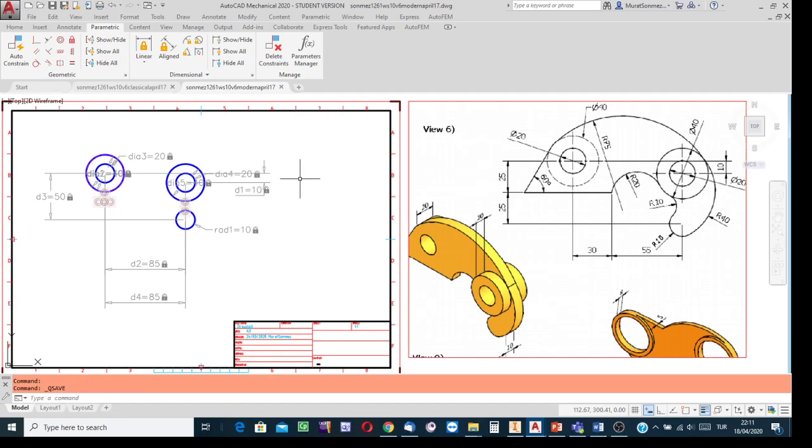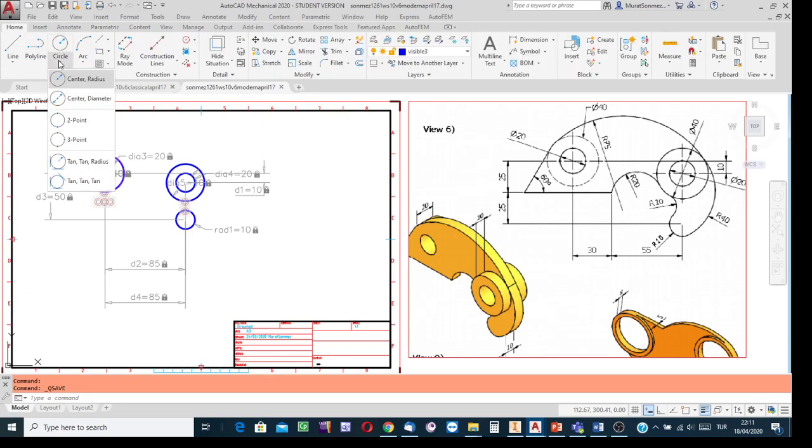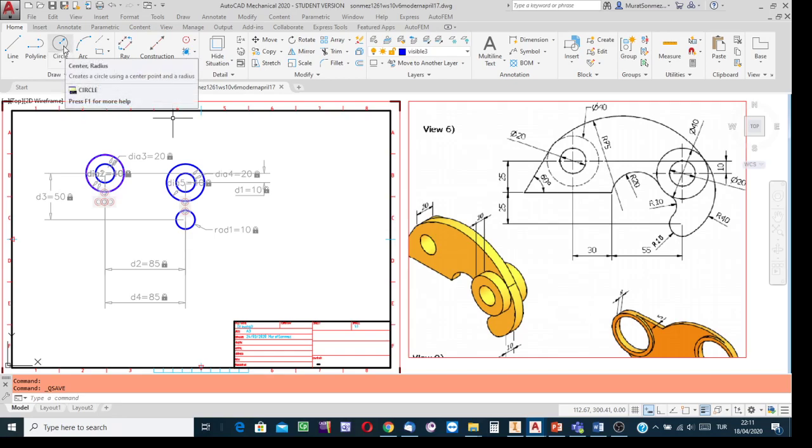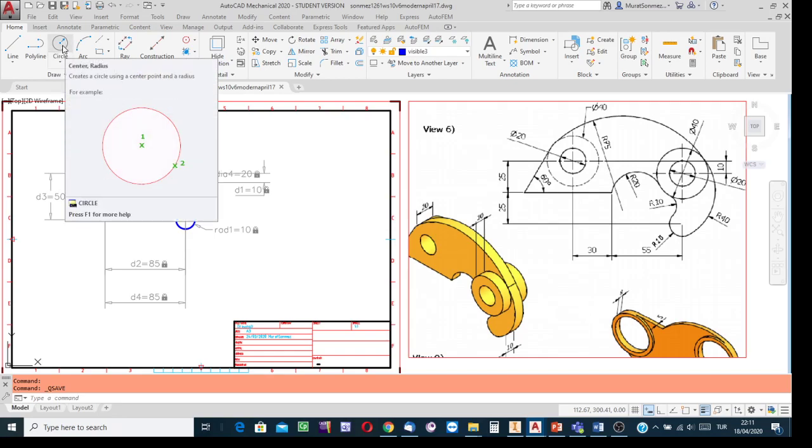And then here I'm going to study the circles, circle arcs, tangent circle arcs. But at the creation stage, those are going to be full circles. They have two tangency relations. Okay, if the method were the classical method, I would say that, yes, use this tool, tangent-tangent-radius. But in applying the modern method, no, it is not the tool of the modern method.